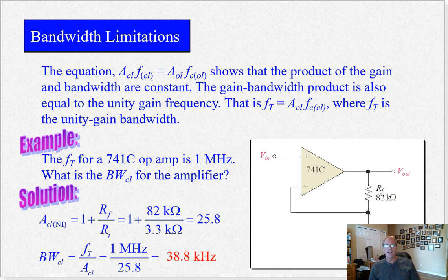Okay, well that's it for today. It's a lot of information for you to soak in. So do the homeworks. There's some good examples in the textbook. I recommend you do all of those. Also start putting together an equation sheet. Write down these equations. This closed loop gain equation for the non-inverting op-amp. Write down the inverting op-amp gain equation, which would be minus RF over RI. Write down this equation and use all of these equations off of your equation sheet to do the examples in the textbook and your homeworks. That's the best way to prepare for an exam, okay?